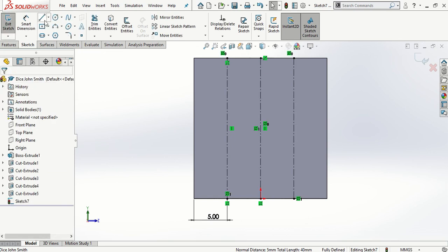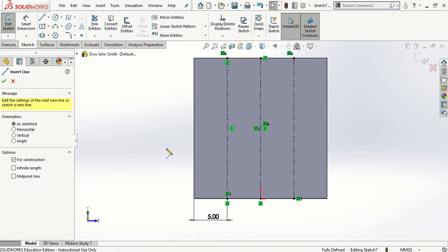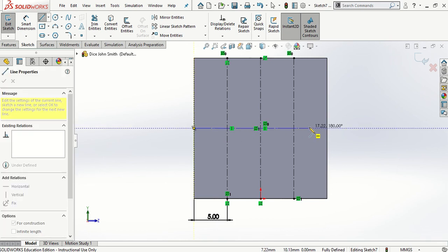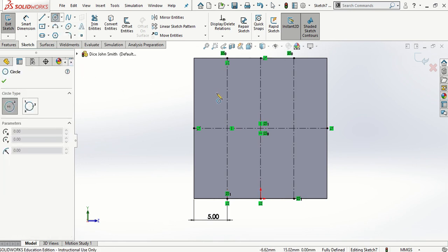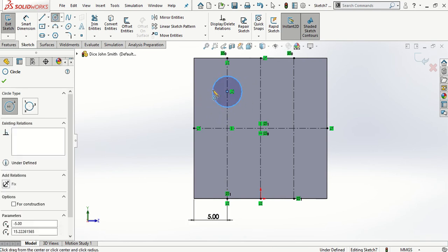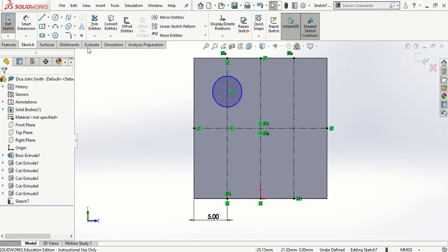And we've one center line to put in. Select this one, and we will have a dot appear here. Click on that dot, that's the halfway mark, and put a center line across to the far dot and escape. So we are ready to start drawing our circles in. So select circle, I'm going to draw it roughly in place here, change it to 4 mil,